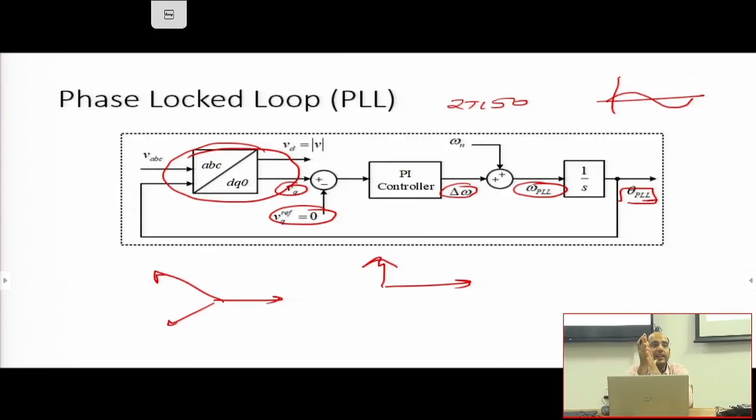So when we align the D axis properly with respect to the A phase axis, that is where we get the desired angle of the reference. So this reference we have to use in all our conversions throughout the control. We should not have different phase angles. Okay. Now once we get the phase angle, we can do the power computation, conversion and everything in all the control. So now we will go into the mathematics of the control.